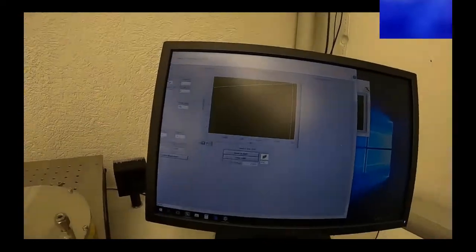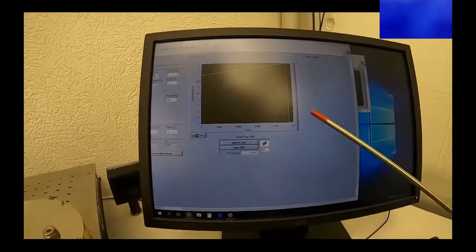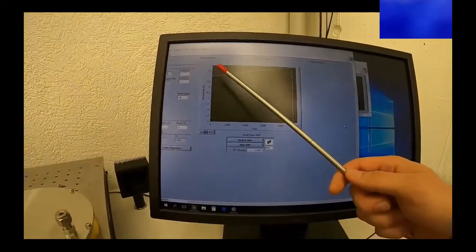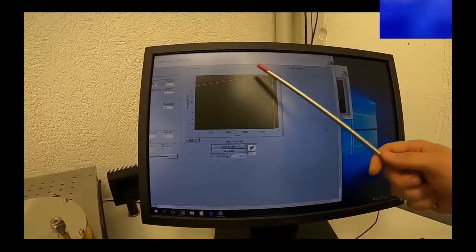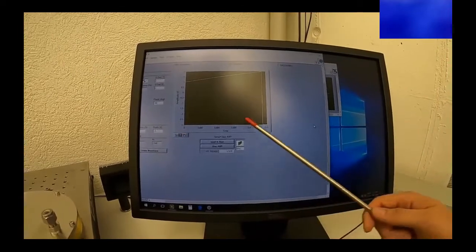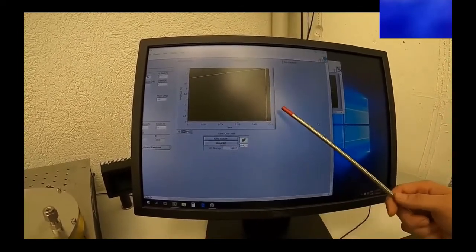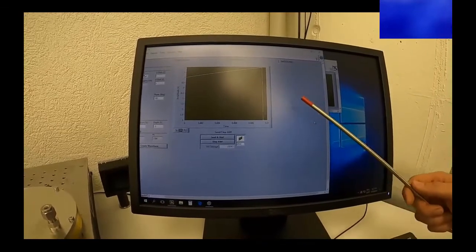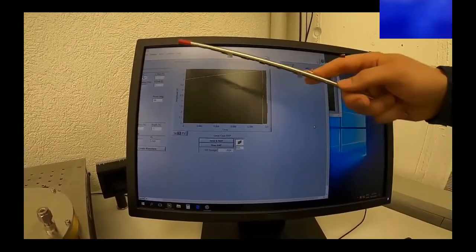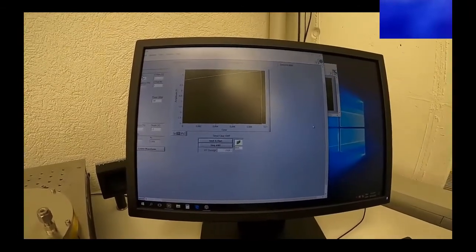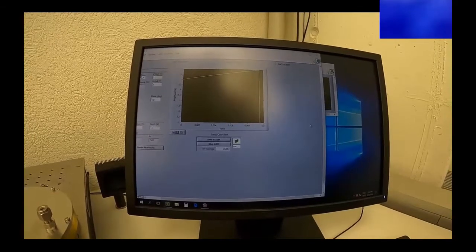We don't have the QCL laser at a stable current, but we sweep the current of the laser in a certain shape, in particular this waveform. Here on the x-axis is time. The entire range is 10 milliseconds, so the frequency is 100 Hertz. On the y-axis, we have the voltage or the current that we put on the QCL.